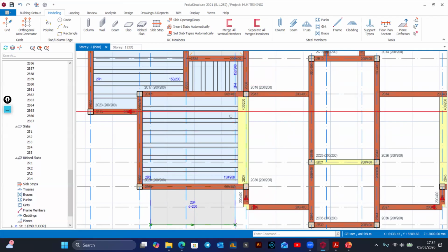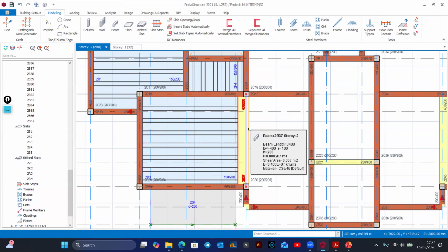So now what is happening here? You have loaded the slab beam with the ribs. Now, a slab beam is going to give you a lot of reinforcements. You may find that even the depth that you added there will be insufficient, demanding you to make a drop beam at this point. Okay? How can we do away from that?